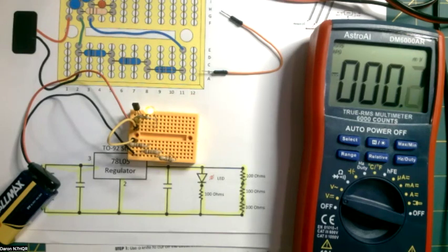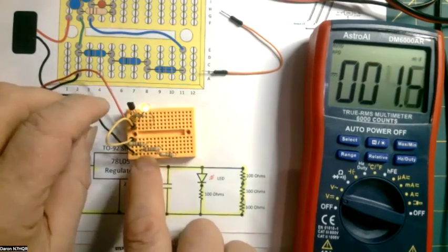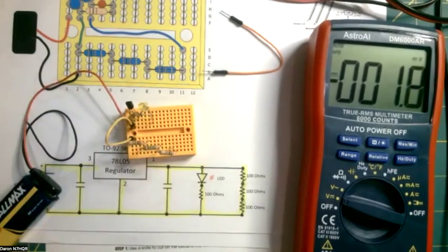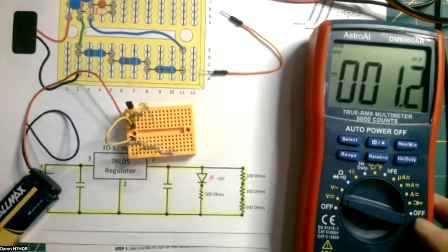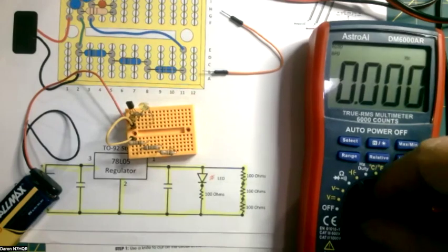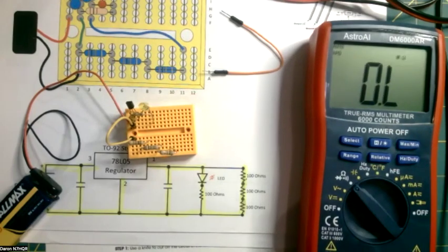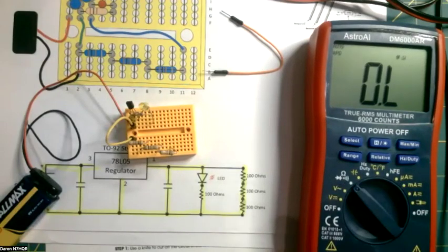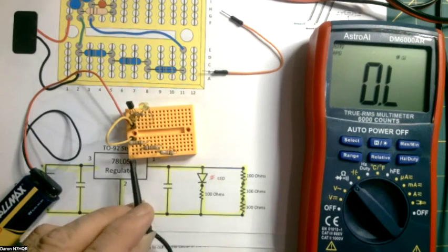Now what I would do is measure the resistance starting at the left-hand side, using your ohm meter to look at it. Okay, so if we're going to measure resistance, we're going to do that without the power on the circuit. So we'll take that little negative wire off, get it out of the way. And we will put the meter on something that looks like resistance. Got the little ohm symbol there, so that should be good.